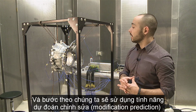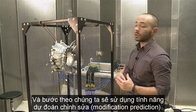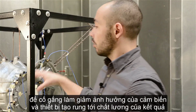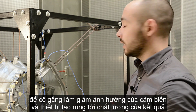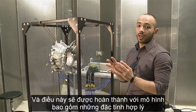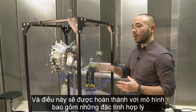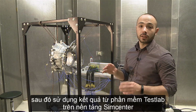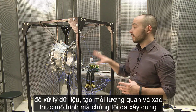So the next step will be the use of modification prediction to try to deduce the effect of the sensors and of the shaker, and then improve the quality of the model again. And once that is done, with the complete model, including the rigid body properties, we will then use the results from Test Lab inside Simcenter to perform a correlation and validate the numerical model that we developed for the gearbox.